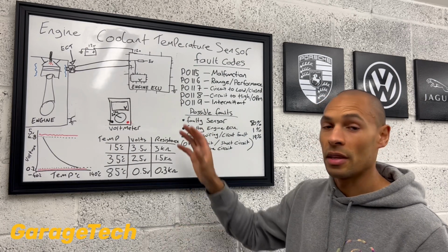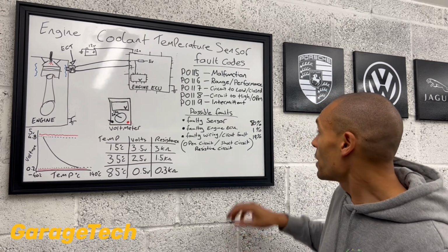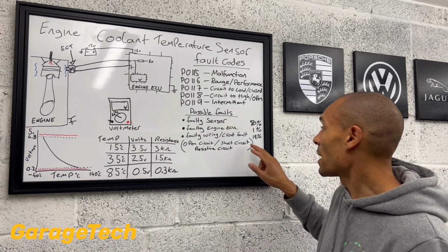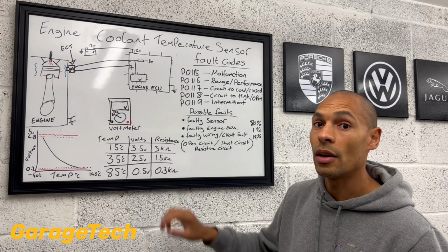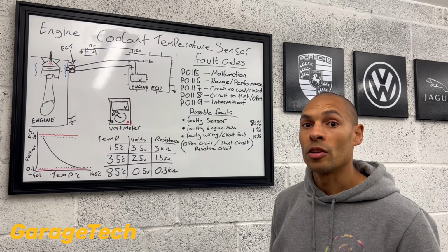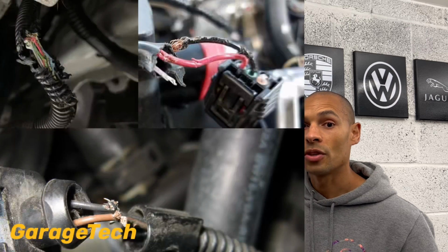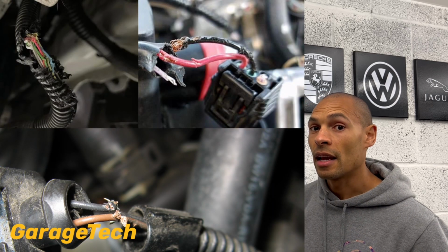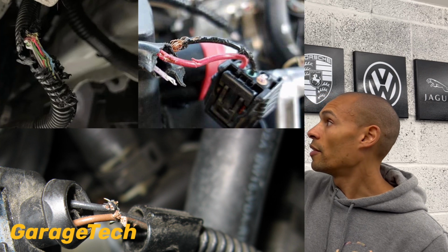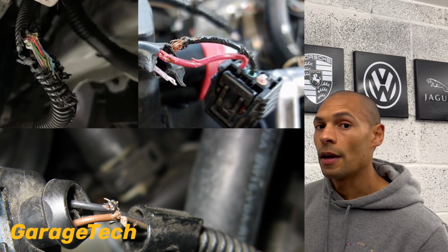And typically if it goes faulty, then you've definitely got some bigger problems than just an engine coolant temperature sensor fault. The other one then is the wiring and the circuit, or the plug connector. That's typically the other thing that starts to go wrong, particularly on older cars, where the wiring's a lot older. Depending on where the car's been stored, it's quite common for rats and the like to get into the engine bays and chew through wiring harnesses. And there are some models of vehicles that have known issues where the wiring is chafed through and broken, which causes a fault with the actual wiring.